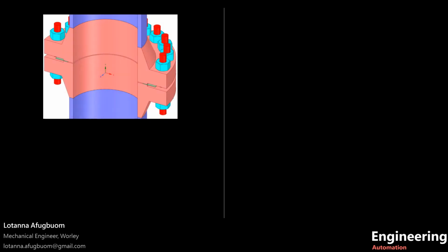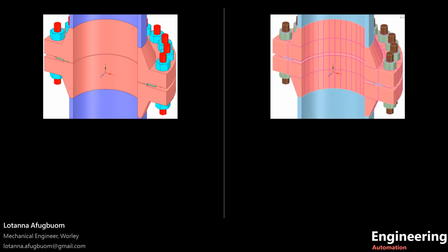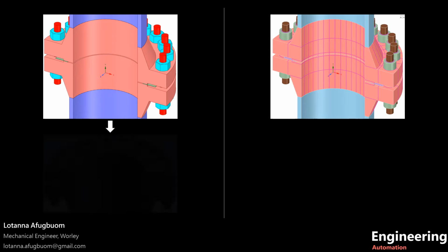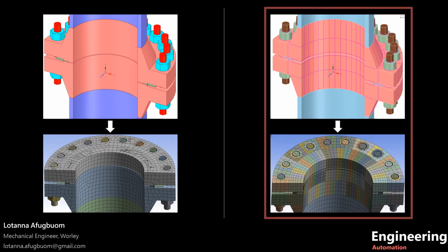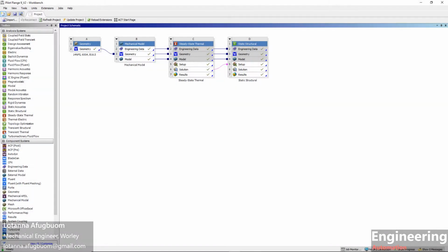The geometrically accurate CAD model was not required, therefore, the CAD model was decomposed to FEA mesh-friendly sweepable bodies and the nuts geometry replaced with a cylinder of similar volume and surface area. The advantage of this approach was the consistent meshing quality. The geometrically accurate CAD model results in poor quality and inconsistent mesh with Jacobian errors, while the FEA-friendly CAD model results in a better quality and structured mesh. The CAD model was then transferred from the geometry component to the mechanical model.